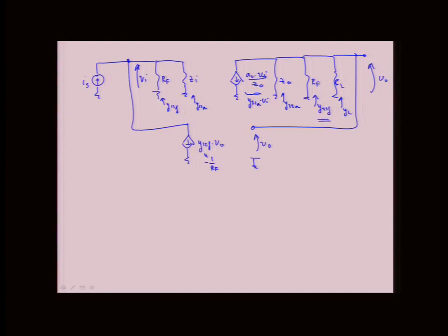Y22 is here. Yeah. I neglected this controlled source, right? Which is Y21F times VI. This one is also minus 1 over RF, right? So it's not clear I should have neglected it, right? But just for the approximation, I do, right?